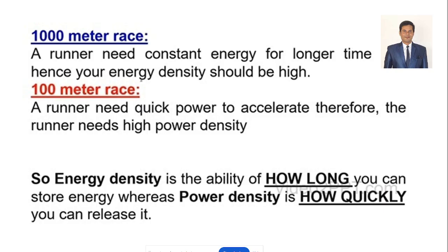That is what I told you: how much charge, how much current you are dealing with for a specific hour. 2 hours, 50 amperes; 1 hour, 25 amperes; 3 hours, 75 amperes, correct? That is how batteries are rated with ampere hours: how long it will give the current to the loads. We require the constant energy for a longer duration.